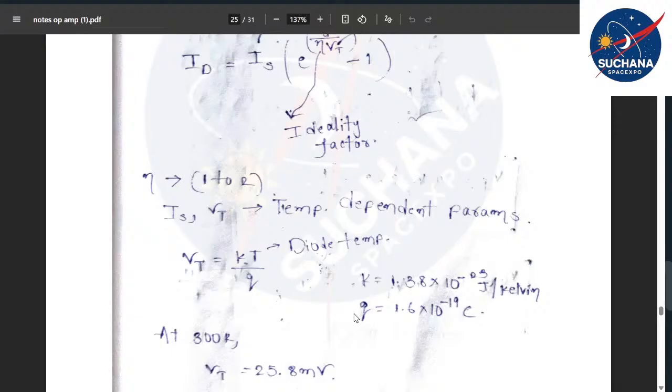Both outputs are different because the slew rate for these two op-amps is different. We have already seen the example of how the slew rate affects the square pulse and the sinusoidal wave. So the output is highly affected by the slew rate, and due to this the output is a little bit different. Some distortion is there. Without knowing this kind of analysis, you cannot directly do that.